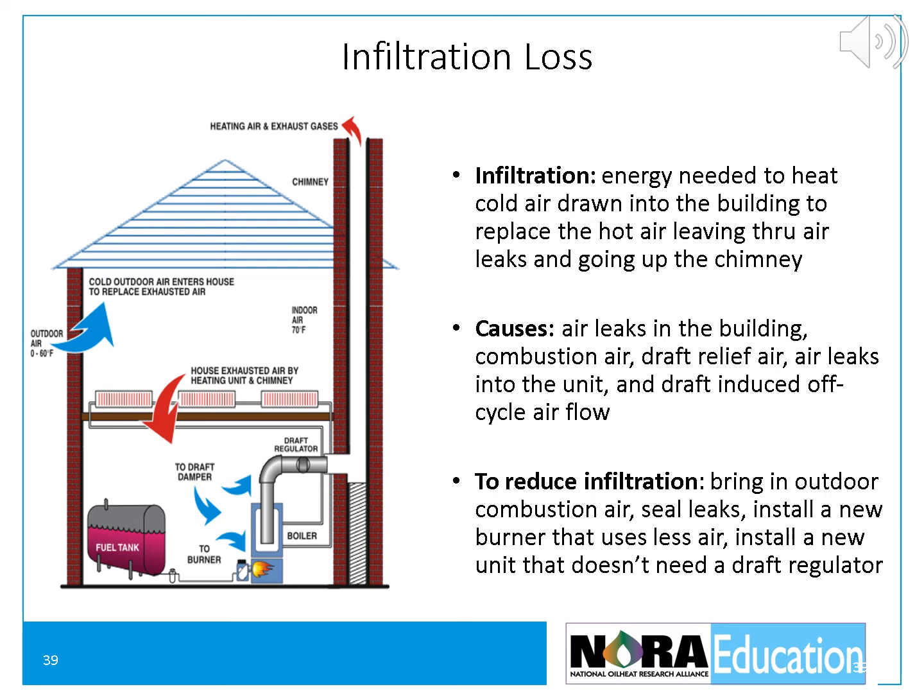But if the burner is located in a confined space, such as a furnace or boiler room, the enclosure must have one permanent opening into the rest of the building near the top and one near the bottom of the enclosure to let in combustion and draft relief air. If the burner is located in a tightly constructed or properly sealed building, outside air should be supplied for combustion.